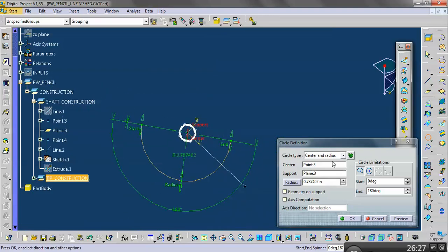And so now we have a couple of options. We can change the angle that we're going to make. So right now we're making an arc, where we want to make a circle, but the arc is the same thing as a circle, just with an angle attached to it. If you want to make a full circle, you can go into this field and say I want to end at 360. I've completed my circle, or the more proper way would be to press the whole circle button.